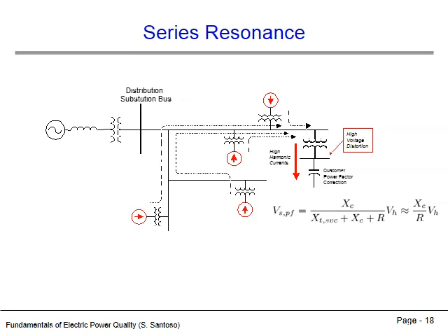Another type of resonance that can occur is called series resonance. This can occur when another customer load contains a service transformer supplying a capacitive element, such as a capacitor bank used for power factor correction purposes. This branch of the system appears to the harmonic current sources as a series LC circuit. Series LC circuits also have a resonant frequency, but at this frequency the inductive and capacitive reactances are equal and opposite. Thus, the impedance in this branch is purely resistive at this frequency, and thus very small.